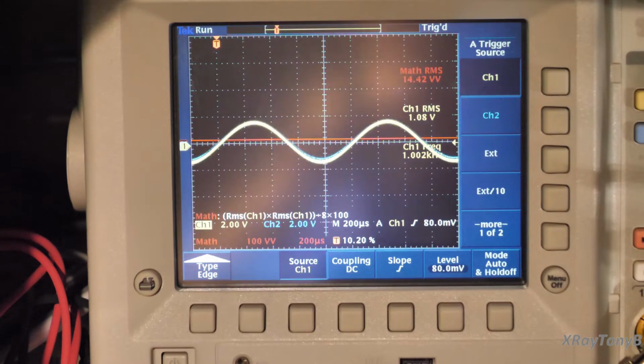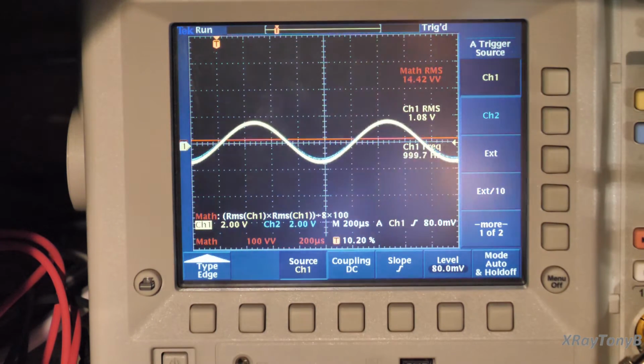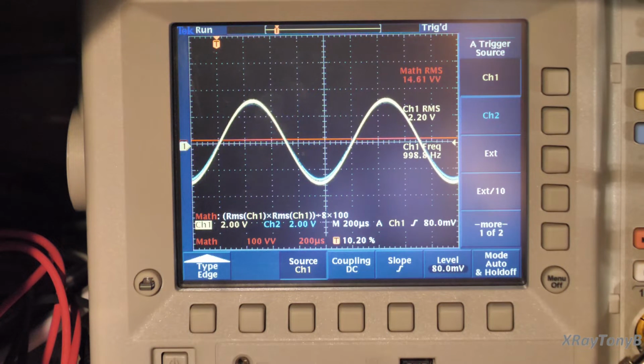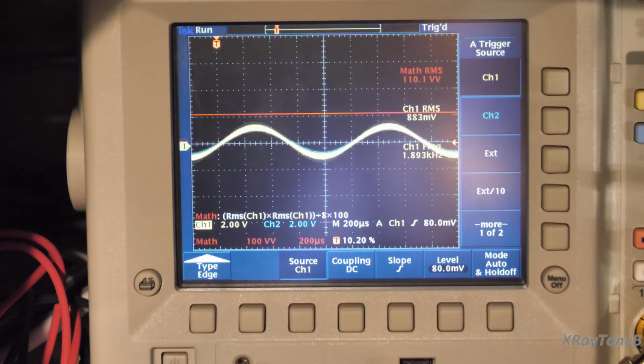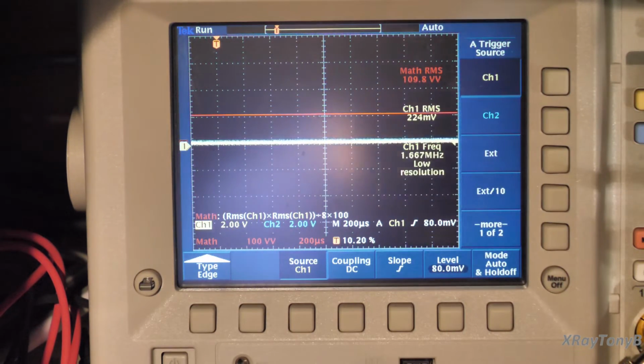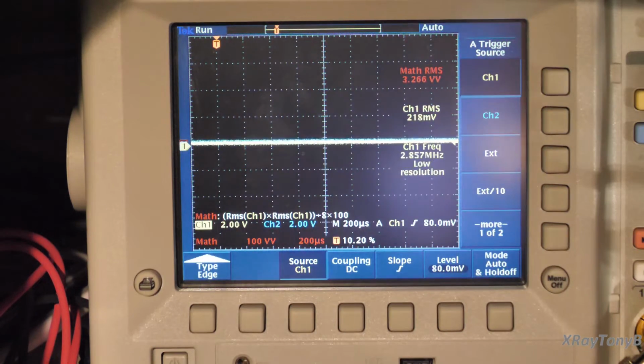14.4. And I'm just going by the detents on the amplifier here. So we're going to do that, and we're going to look at the harmonic distortion. And then we're going to go somewhere around 50 or 60 watts per channel, which is right about here. That's 60 watts per channel. And then we're going to go to about 108 watts per channel. I believe it's going to be somewhere in the 100. Yeah, 110. There's your 110 watts per channel right there. So we're going to look at those 3 levels and see where our total harmonic distortion is.